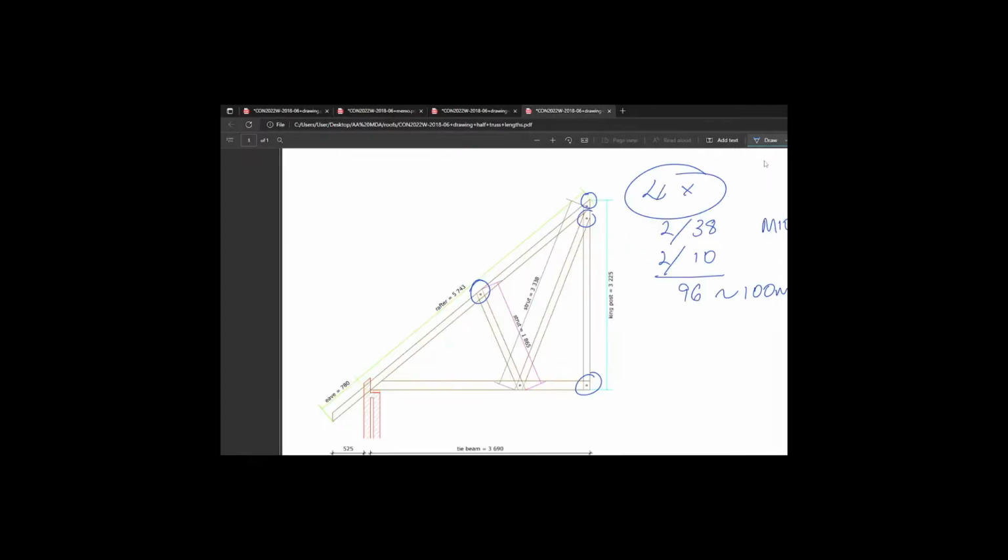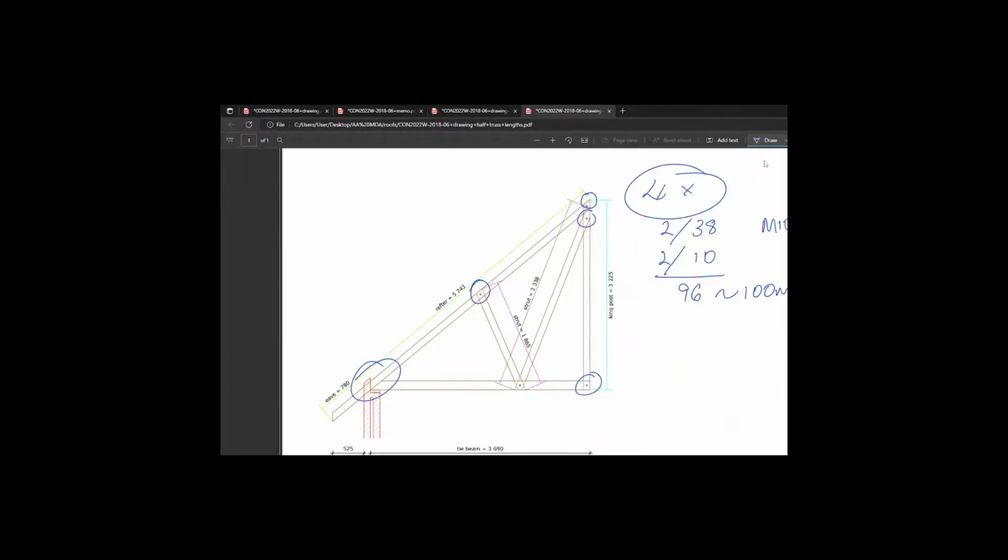And M16, we'll do the same. The last bolt left in this diagram, remember, this is still, have we done nail plates? I brushed over it, I'll come back to it. Let's finish our M16 though for now. The only M16 here is this one, 3x38 and 2x16, because this number is over 100 already. And there's only 1 per half truss, and there's 10 total. Here's our 140, this is 3x38, 2x16. I'm not sure what that exact number is, but it will not be exactly 140, we round it up or down to 140.